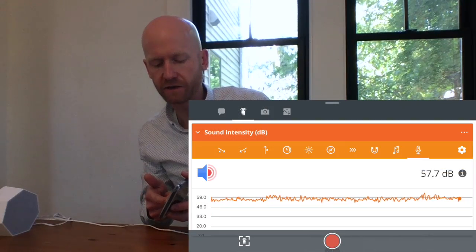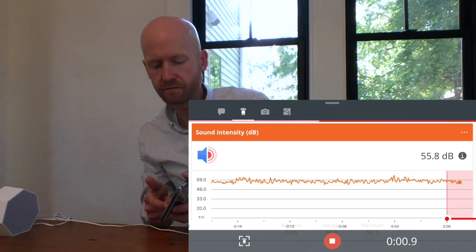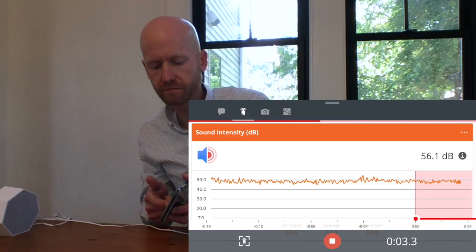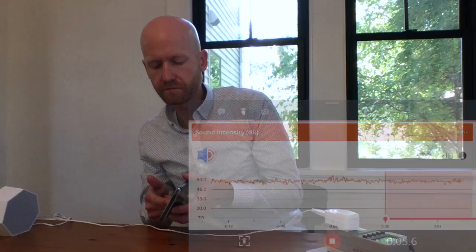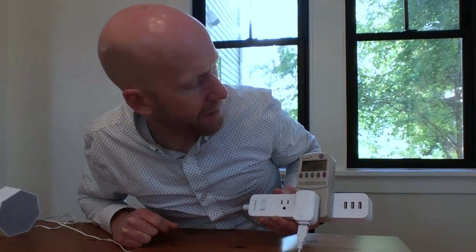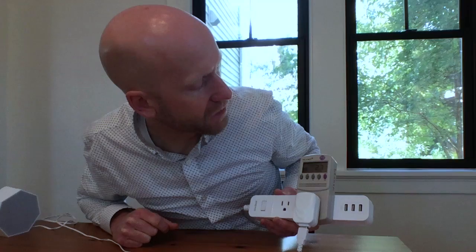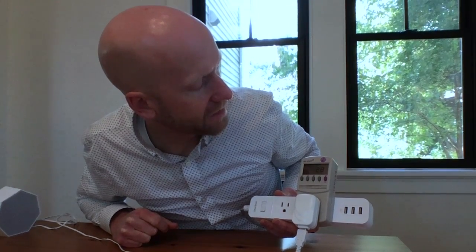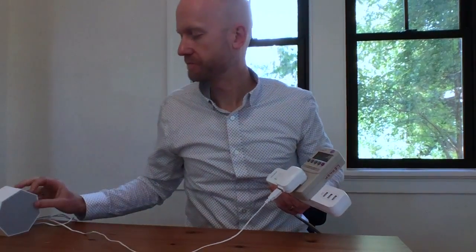And I'm going to want to adjust the intensity of this to try to match the medium setting, which was like 58, 59 decibels. I'm going to go ahead and take a 5-second average to make sure that it's about right. And what we can see for power is we're consuming about 2.8 watts. So I'm going to put 2.8 into my spreadsheet.